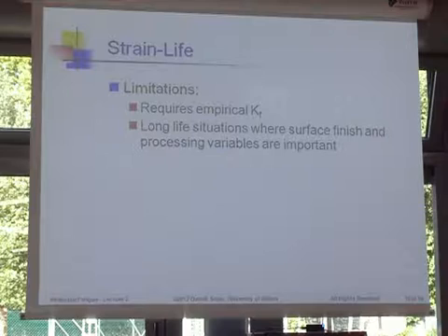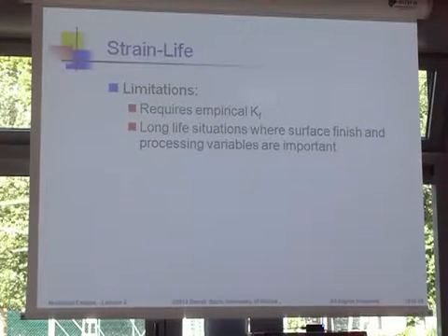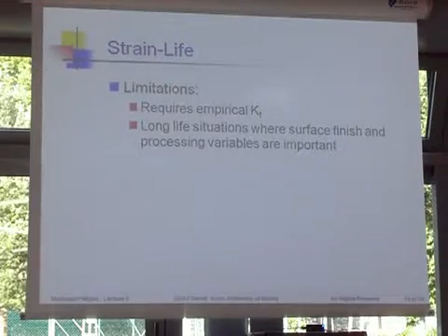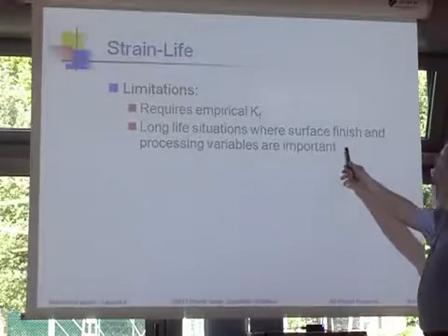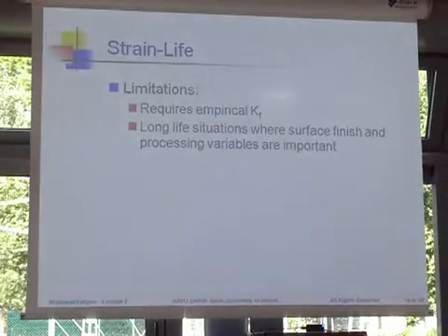So there are some limitations, of course. This idea about how to deal with notches is still largely empirical, and I just put that as an empirical notch factor. And the other place this doesn't work very well is in long life situations where surface finish and processing variables are very, very important.